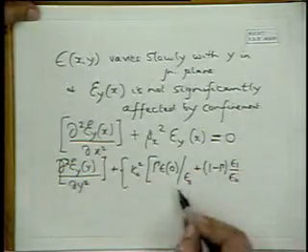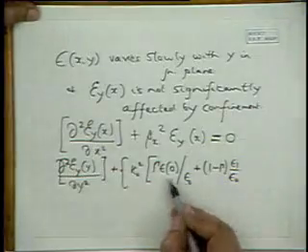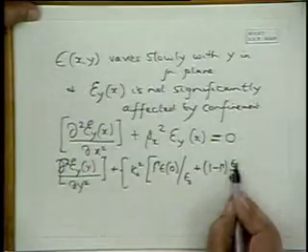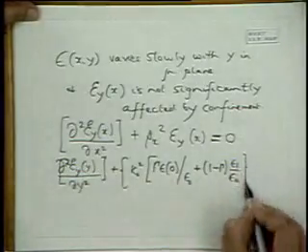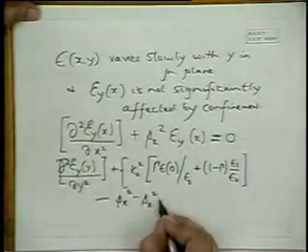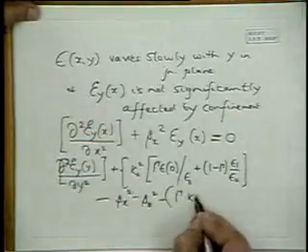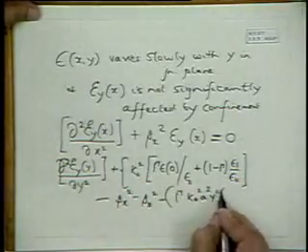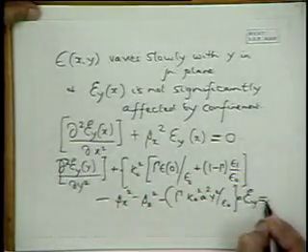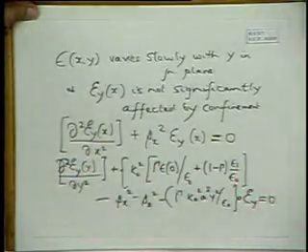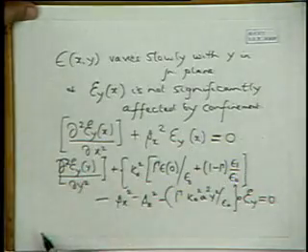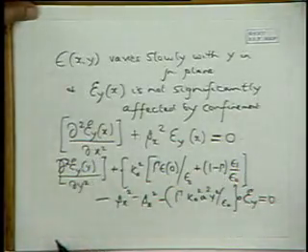So in the case of multi-quantum well lasers, we'll find out that within the active region it's gamma into epsilon, and outside the active region it's 1 minus gamma into epsilon 1. And the other terms, minus beta x squared minus beta z squared minus gamma k0 squared a squared y squared by epsilon 0, Ey is equal to 0. So this is the final field distribution, variation in y, Ey, the electric field in the y direction.